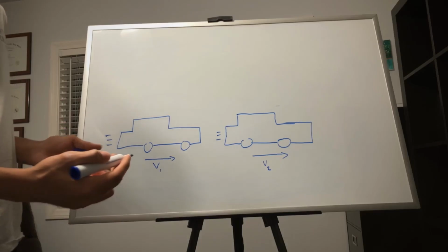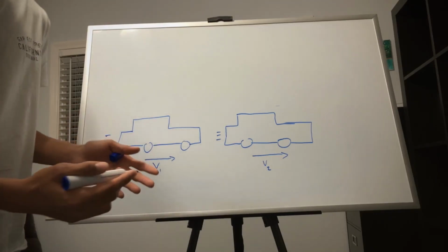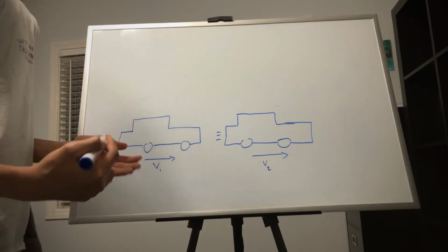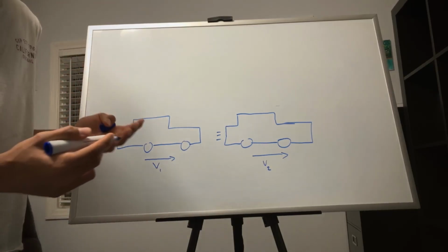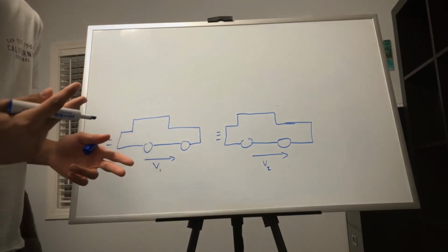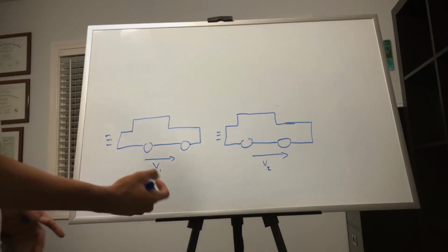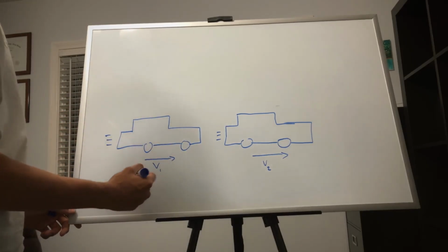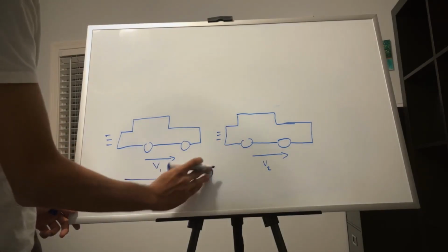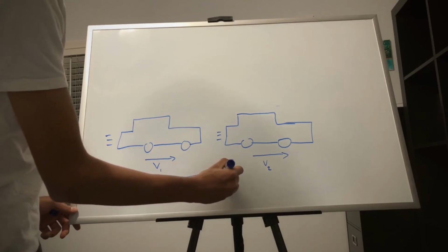So if we were to use our traditional proportional derivative controller, as we've seen before, remember that from the previous situation with the two stoplights, basically the car would speed up and then slow down as it approached the second stoplight. In this situation, that's not what we want, because our car is going to speed up to some speed, and then it's going to reach some position, getting closer and closer to the second car.